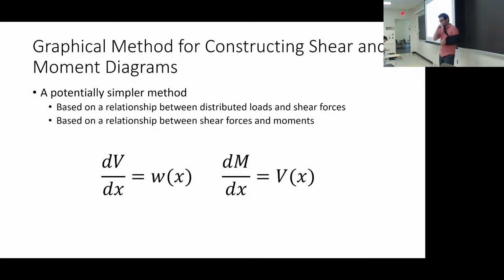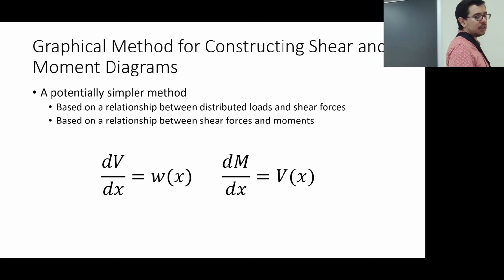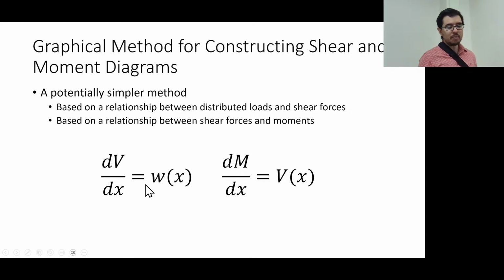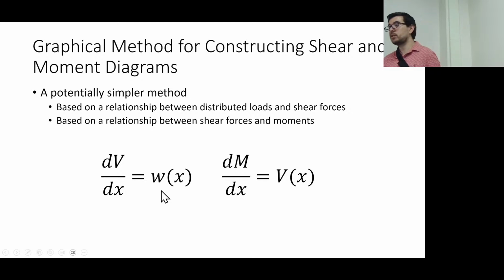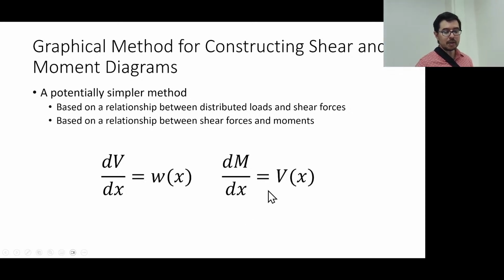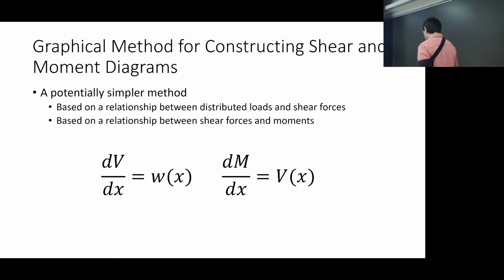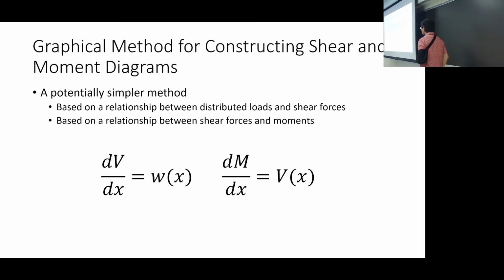In words, what the equation on the left says is that the derivative of the internal shear force with respect to x is equal to the distributed force. And the other one is that the derivative of the moment with respect to x is equal to the shear force.